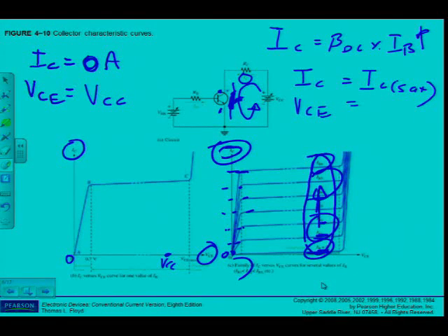Now, what we've seen, a forward bias diode gives me a volt drop of approximately 0.7 volts because it's not an ideal device. Now, the same happens for the transistor. The voltage is a bit different though. It's not going to be 0.7 volts because we're talking about 2 p-n junctions. You will see in this book, but I will mention it again. It should be 0. Closed switch should be 0. So VCE should be 0. But because it's not an ideal device, we will assume, unless otherwise mentioned, that it will be approximately 0.2 volts.